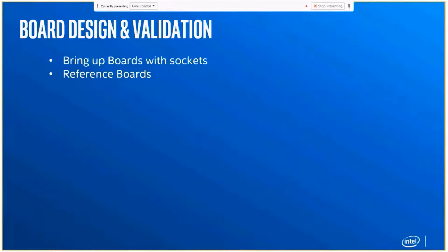Instead of that, Intel itself does what are called reference boards. So these are functionally similar to what the customer would want to do, right? So take SNR. It has so many blocks that we need to verify. So the main board, the Victoria Canyon that we are working on, has a lot of connectivity, a lot of pins, a lot of interfaces where you can connect debug tools, utilities, and try to figure out if the chip is working properly. But you can imagine, why would Nokia or Ericsson want that? They want a board this size with bare minimum stuff, and that's it, right? So we also do that kind of boards, and we give that to our customers.